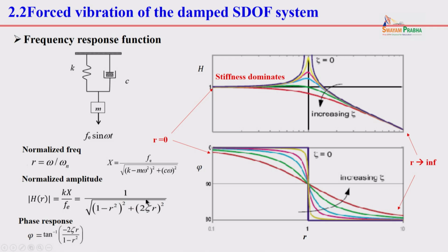Therefore, damping wouldn't matter. So at that frequency, everything goes to one line. That is mass dominated. You see here, this term is omega to the power 2 and this term is omega to the power 4, and for the omega to the power 4 term, the coefficient is m. Therefore, mass matters.